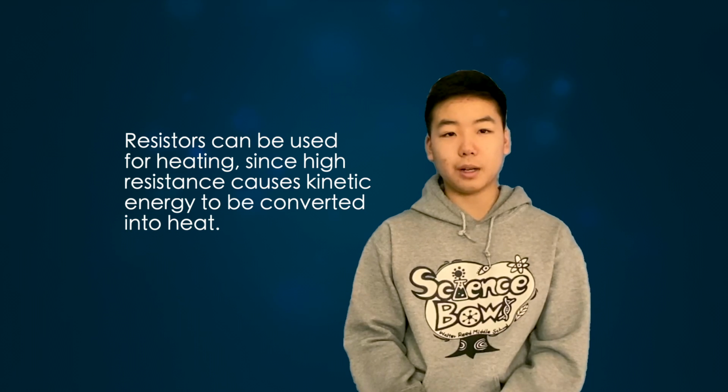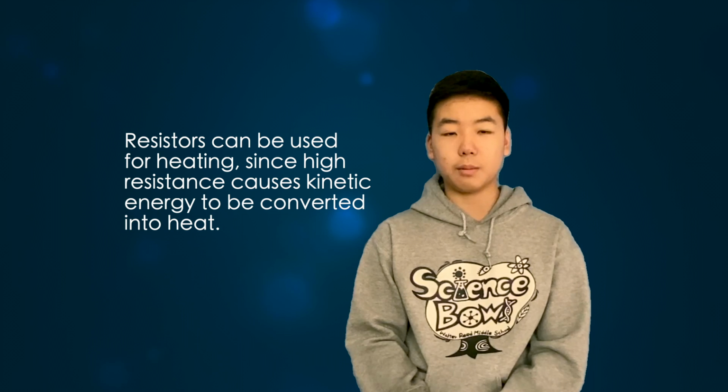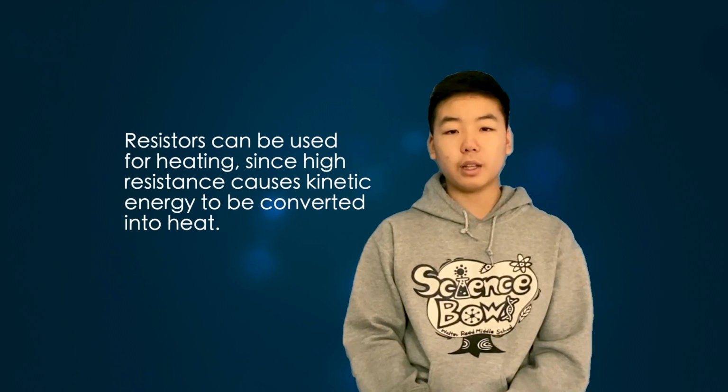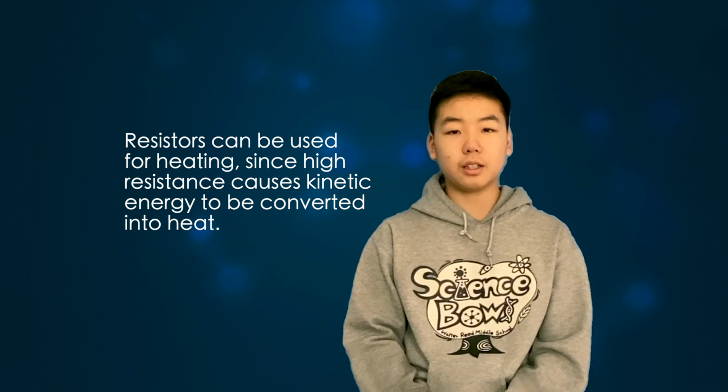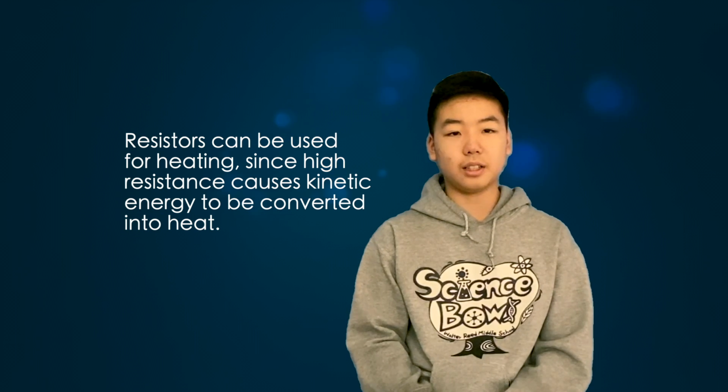Another use for a resistor would be heating. When electrons try to pass through something with high resistance, they constantly crash into atoms in the object. Remember that energy cannot be created, but only transformed into other forms. So when electrons crash into the atoms, their kinetic energy is converted into heat. Circuits often take advantage of this fact in everyday life. For example, toasters use this mechanism. Their wires are specifically designed to have high resistance so that they can generate heat and toast your bread.